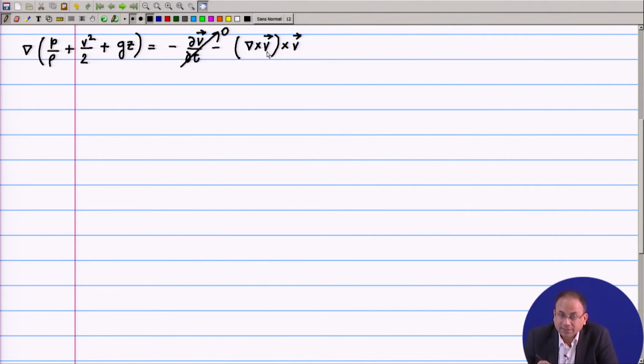If the flow field is irrotational, then this term, which is known as the vorticity, vanishes. Given a velocity field, you can find the vorticity field. If you are given V, you can just run a cross product between this operator and the V vector, and you get the vorticity vector or vorticity distribution.